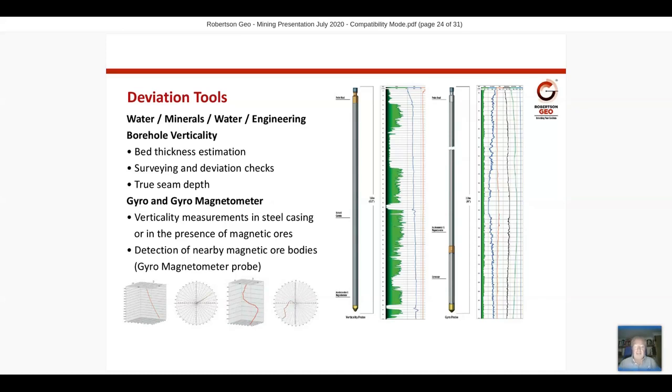if you take a look at the third image along from the left, which shows a track of a deviated corkscrewing borehole, which is quite often more the reality of the types of boreholes that are produced, then they're not always nice, smooth, cylindrical features that are dead vertical. So borehole verticality is critical in determining deviation and from that TVD in relation to measured depth.